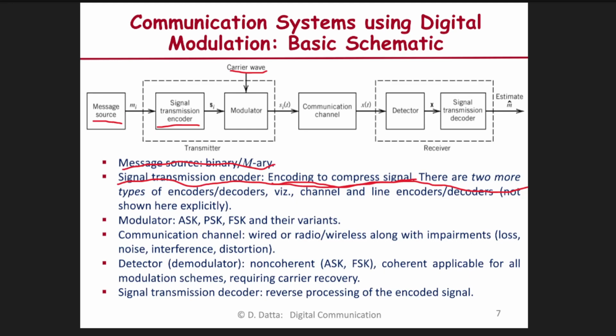So if you want to code against the channel noise, you have to have some redundancy. So you reduce the redundancy in source coding in the original source, and while doing the channel coding, which will fight against the channel noise, you can add some additional bits and make it more robust against the noise. So these two things go together.